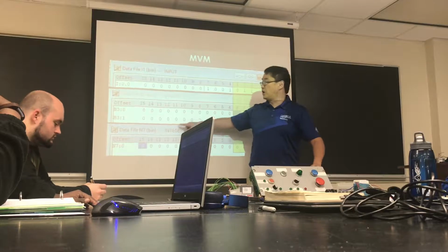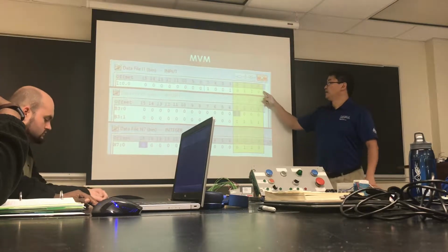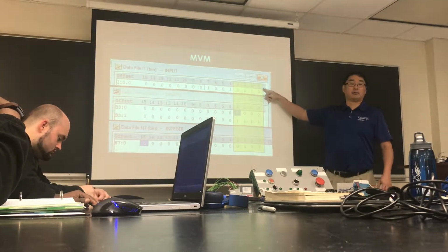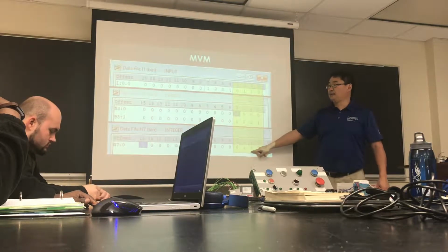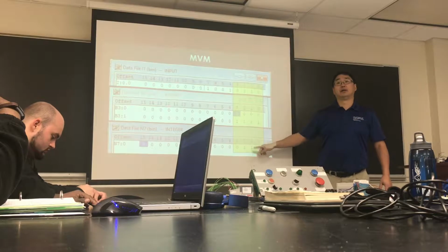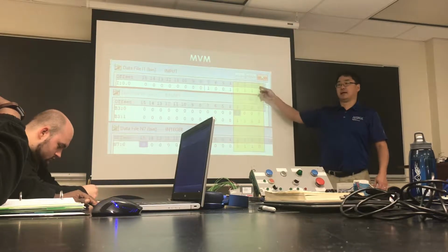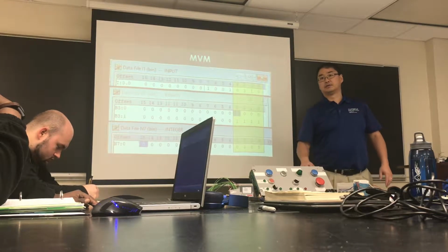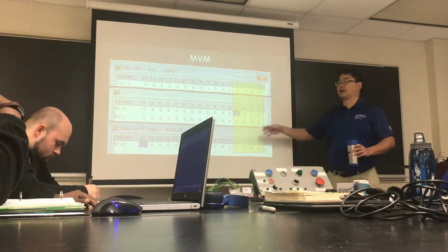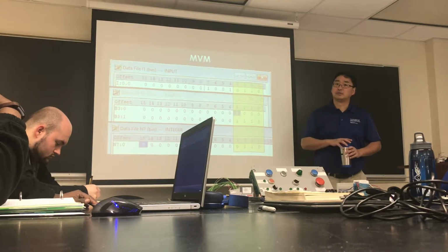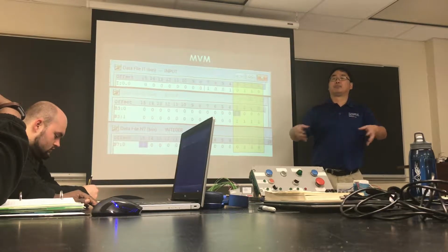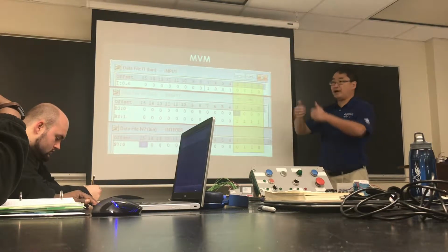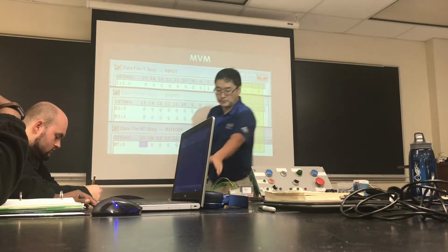Okay. And so this way, I can take these 4 inputs, which are my BCD inputs, and copy them down to a number, and now I can deal with it as a number instead of as bits. Does that make sense? And you would do this if you're doing part numbers. If you're saying, okay, start model number or part number of 12, you dial in 12 on the thumb wheel.